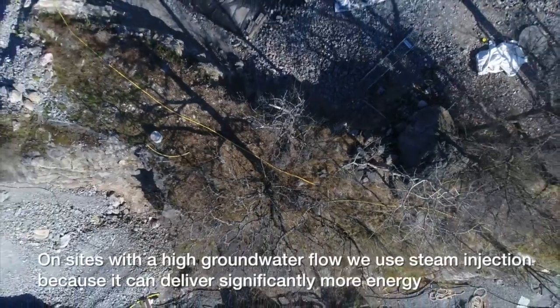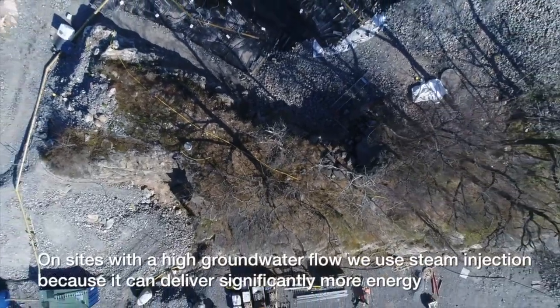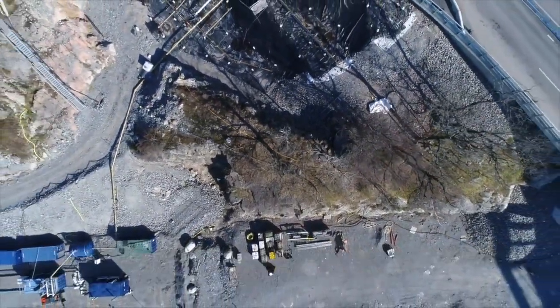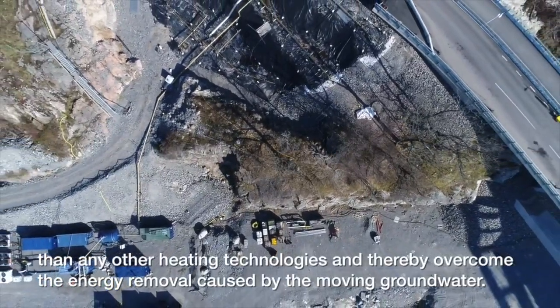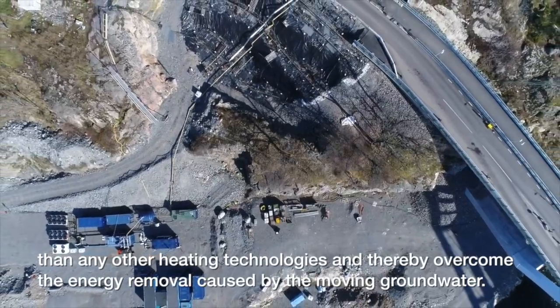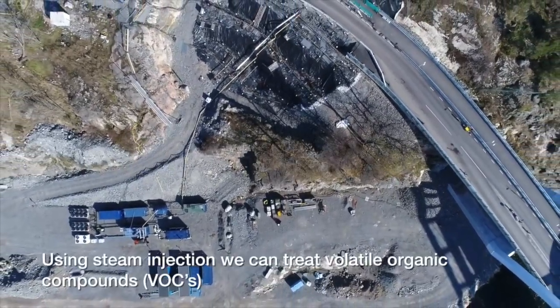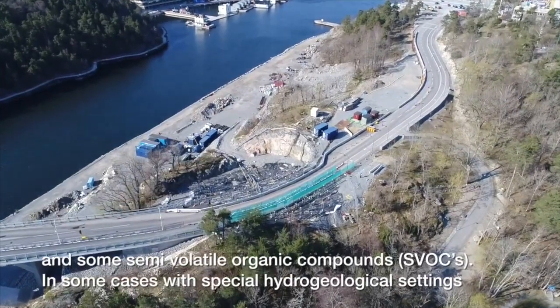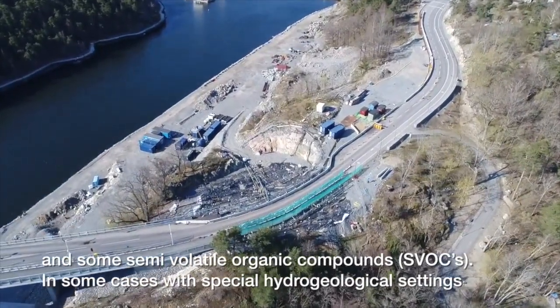On sites with a high groundwater flow, we use steam injection because it can deliver significantly more energy than any other heating technologies and thereby overcome the energy removal caused by the moving groundwater. Using steam injection, we can treat volatile organic compounds and some semi-volatile organic compounds.